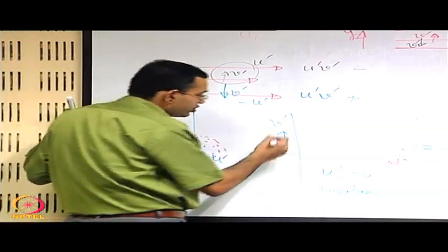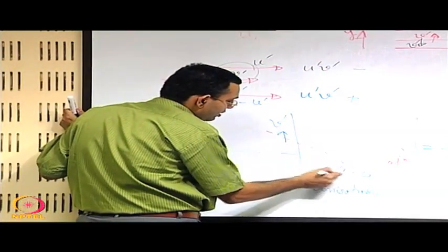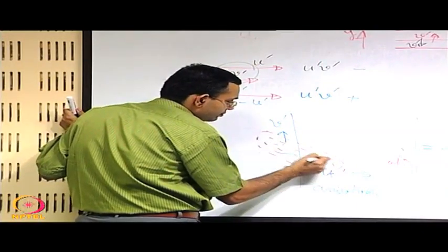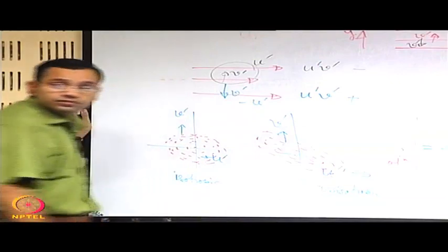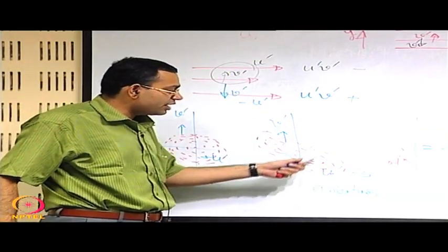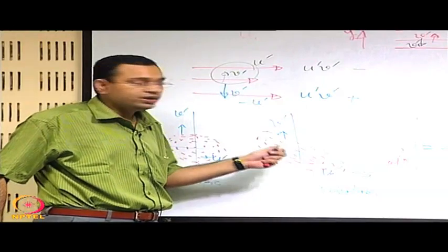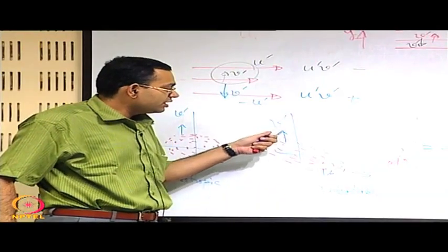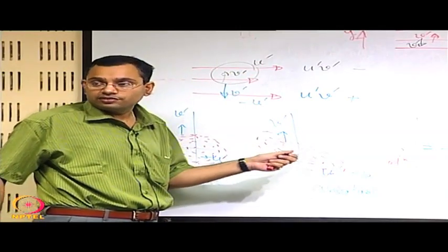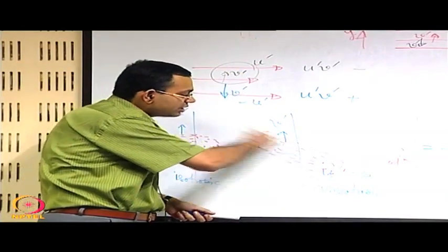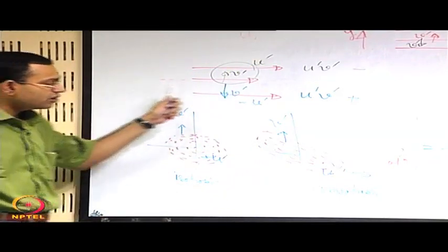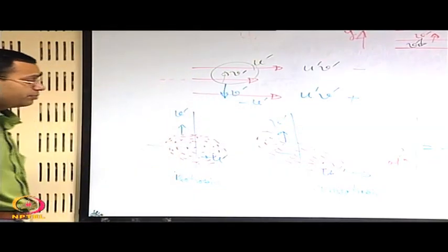However, when it is anisotropic, the scatter of points may be like this. And why is it scattered like this? Because if you calculate the correlation between the two, we have seen that u prime v prime average has a negative correlation, and that is why if you fit a regression line, it will have a negative slope, and that is why this will be the scatter diagram for the anisotropic one.